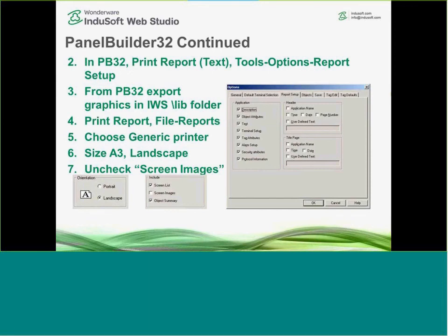There'll be a lib folder in there, and that's where you're going to export your graphics. That has to be done one by one if you have graphics, bitmaps for example. It's a simple click export, but you have to do that one by one. That's a limitation in the PanelBuilder32 software.